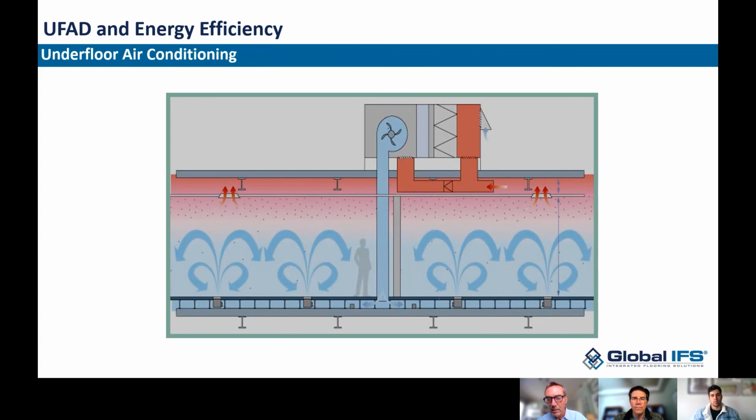We eliminate almost all the ducts, and we're delivering the air through pressure-dependent diffusers like you see here, but the air is warmer. Big difference here is that the air is warmer because we don't want to deliver 55-degree air at the space or into the space at people's feet. It would be uncomfortable. So typically we're going to deliver that air slightly warmer, about 62 or so at the carpet. It gains heat as it gets into the space pretty quickly.